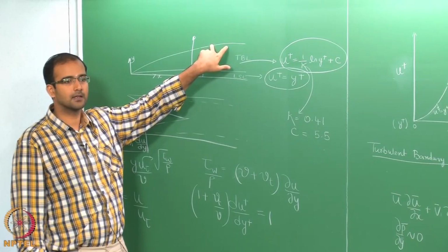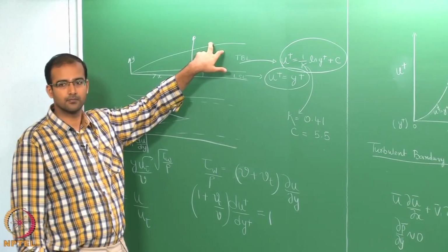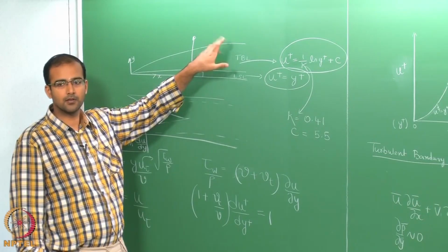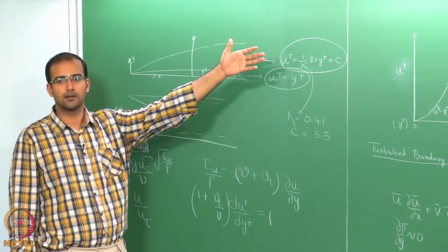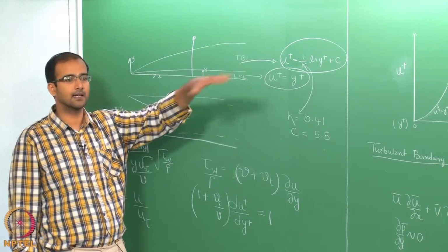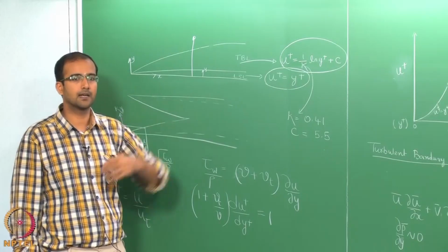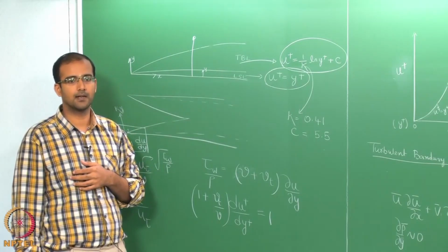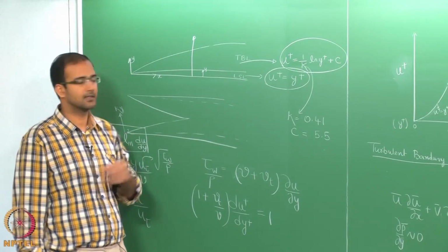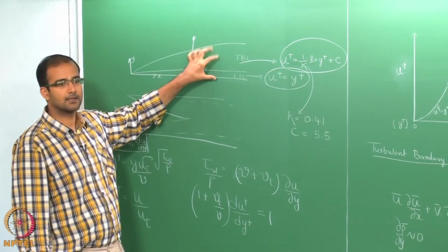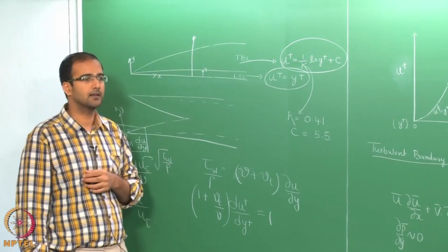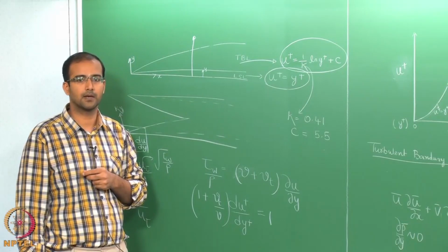So, this is governed by the turbulent Prandtl number. Okay. So, now the question becomes whether I can use the energy integral and integrate it up to delta t, and what is delta t here? Is it only within the laminar sublayer or up to the edge of the turbulent boundary layer? So, that becomes a problem.